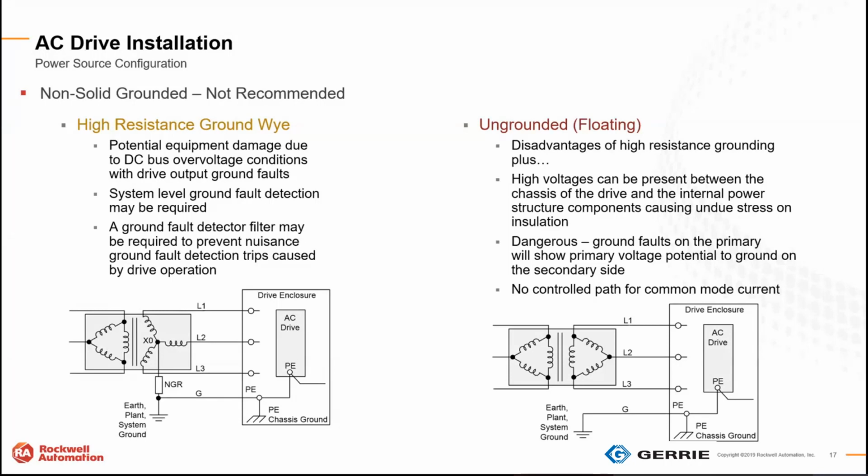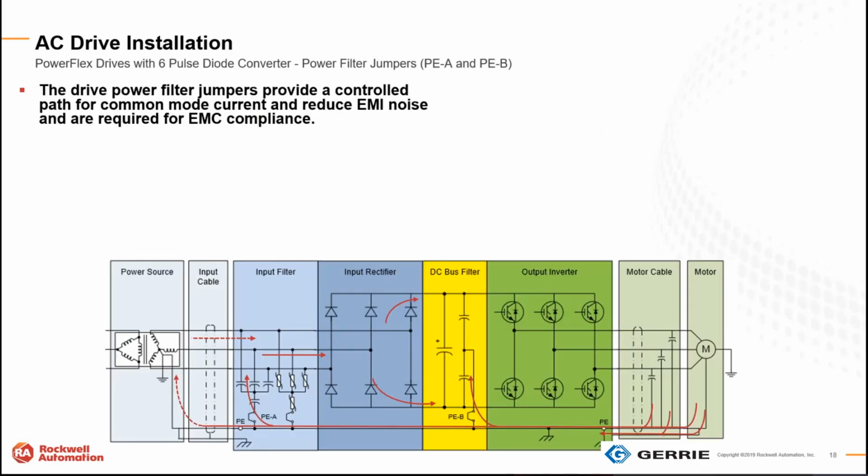We can get some high voltages present between the chassis of the drive and the internal power structure, and oftentimes we see flashovers and a lot of stress on the components in the DC bus for that application. So we just don't like seeing that one.